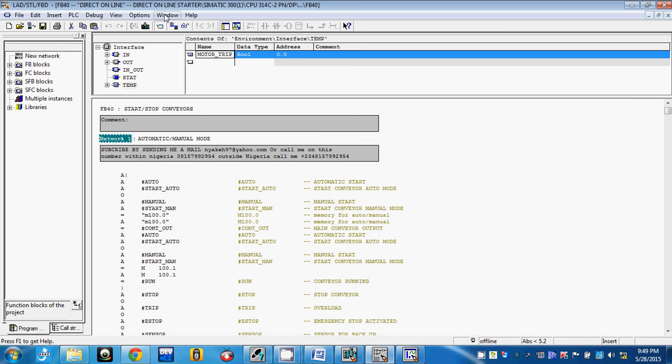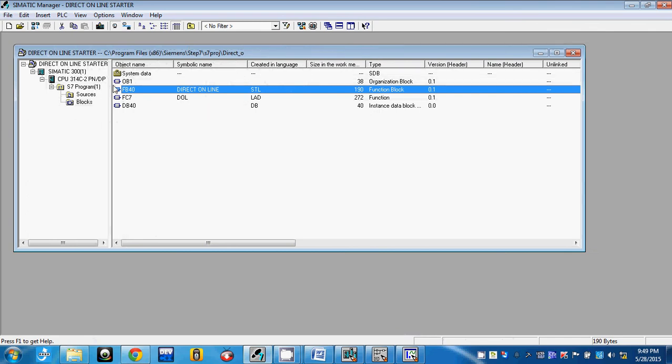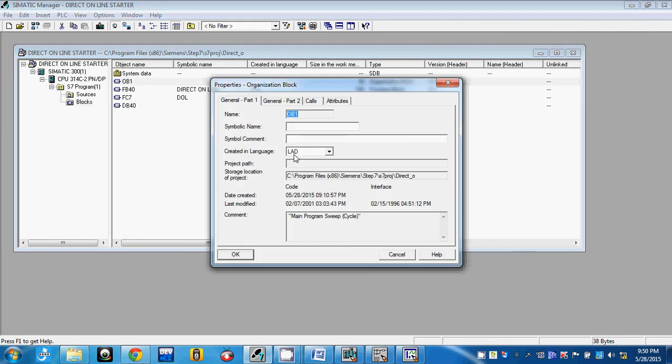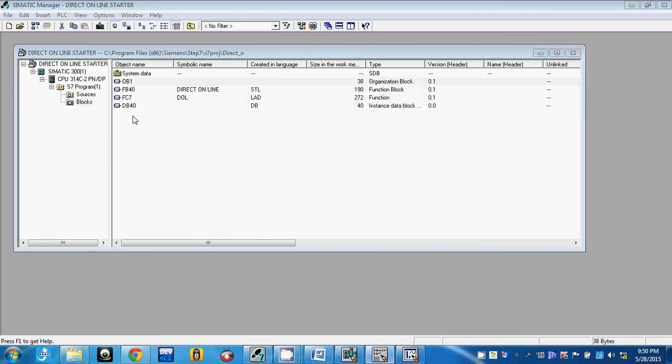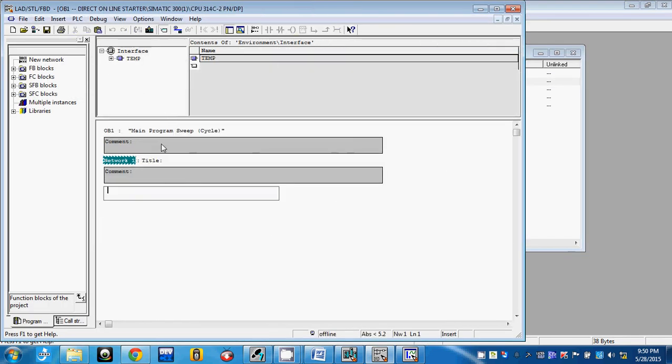Okay. So what we're going to do now, we're going to open OB1. Then we're going to call FC7. Okay. Save.